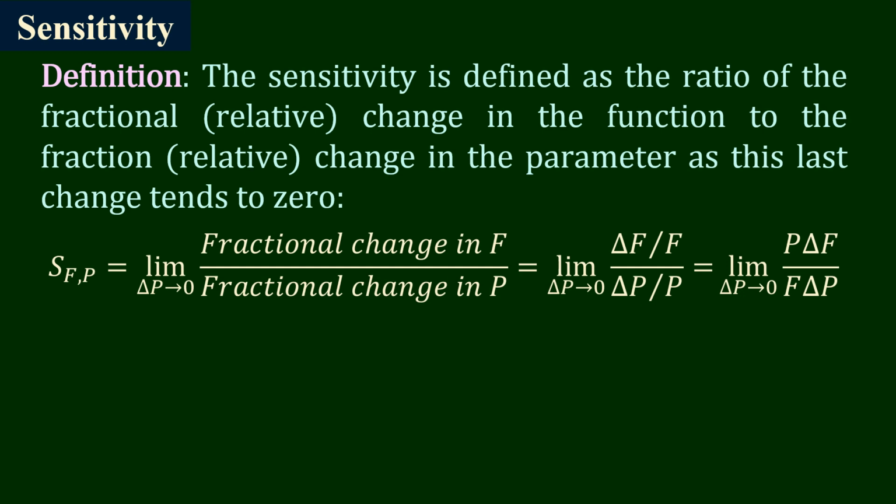We define the sensitivity of a function, by definition, for a small change in the parameter which tends to 0, as the fractional change in f due to a fractional change in p. P is the parameter. So if the parameter is changing, what will change in f? We can write the fractional change as the limit of delta p tends to 0 of (delta f upon f) divided by (delta p upon p).